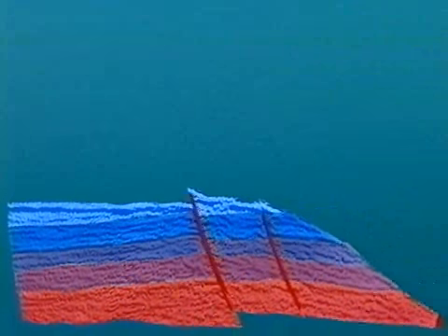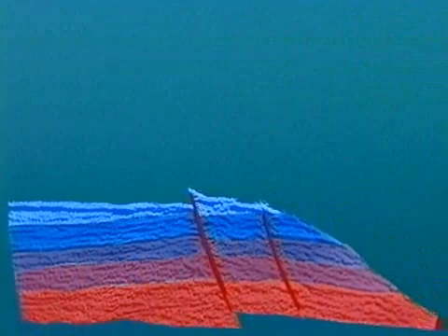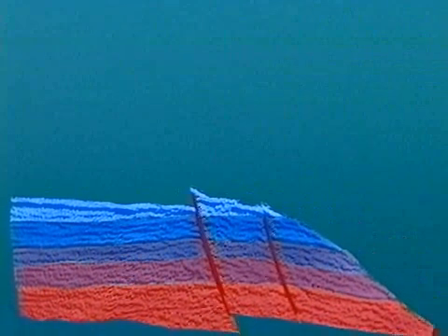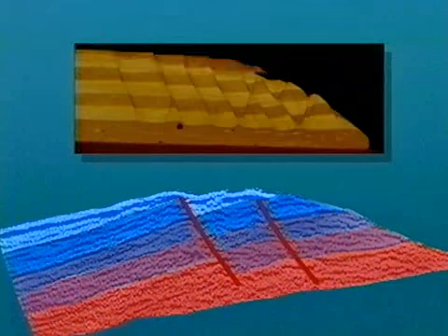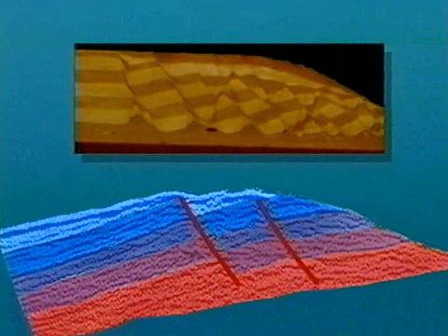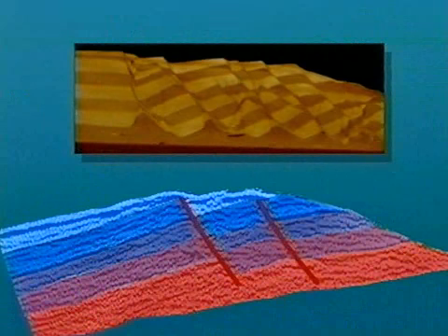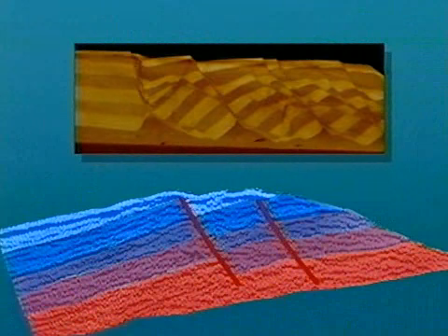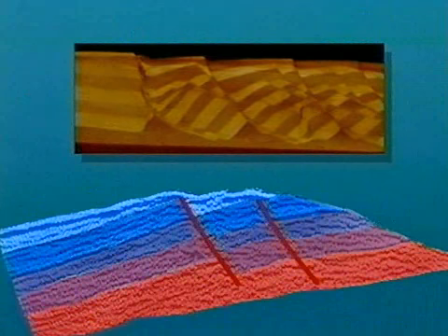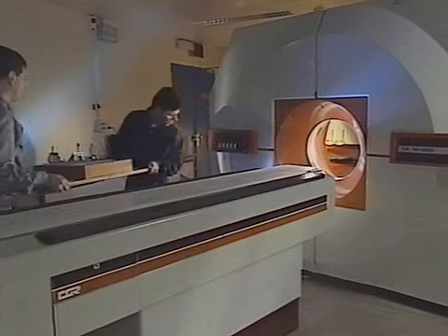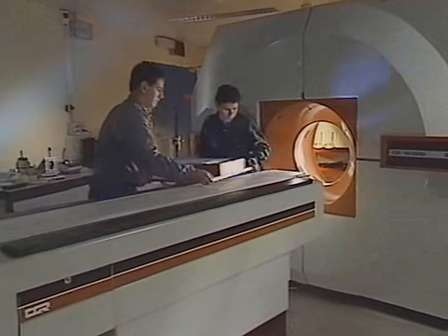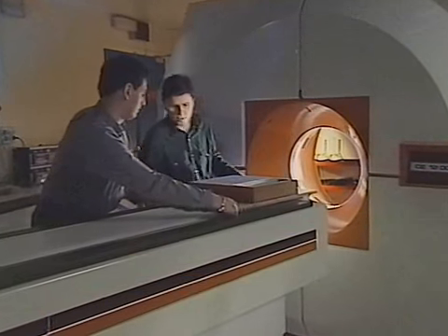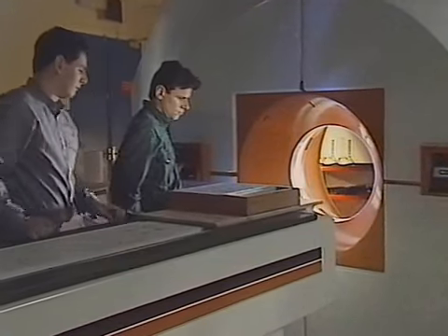What are the geometrical and mechanical rules for the occurrence of these traps? What is the three-dimensional geometry of the fault pattern? To understand the extensional mechanisms, we did a series of sandbox experiments analyzed by X-ray tomography, examining the complete evolution of normal faults and investigating the three-dimensional geometry of structures. The sandbox experiments were carried out in the acquisition field of a medical X-ray scanner so as to visualize cross-sections of the model during deformation.